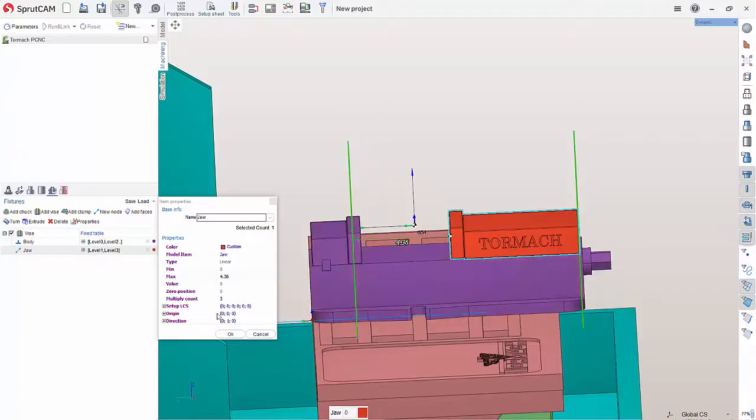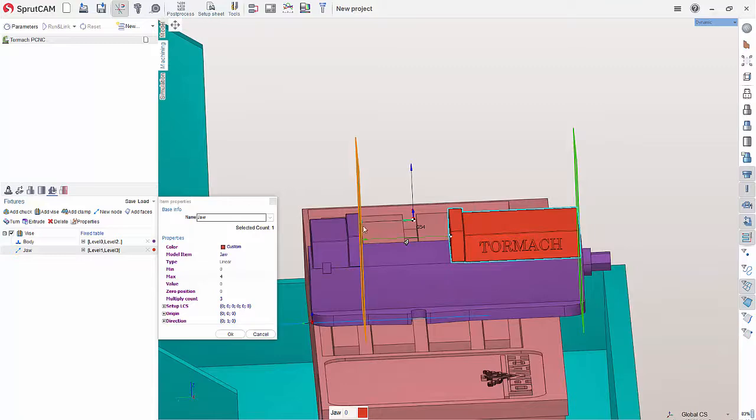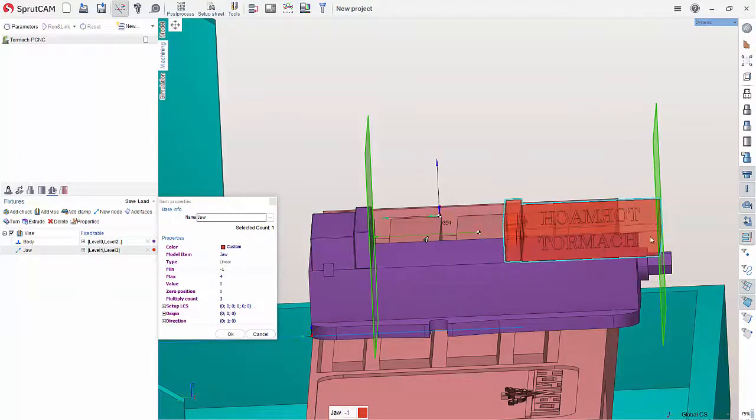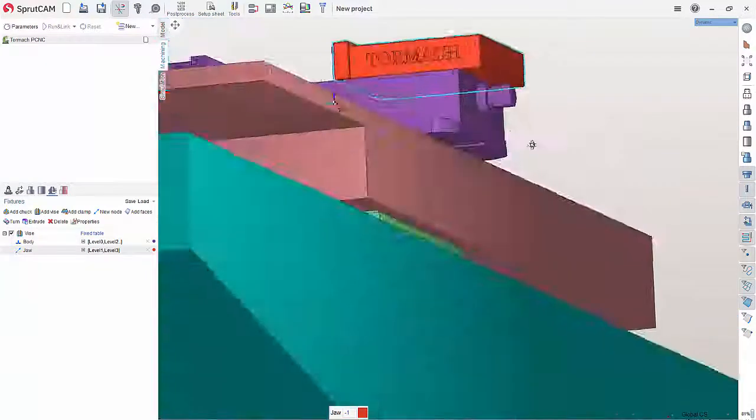Okay, but we want this to be a 4, and that'll take us right up to that point right there. And then because this is a 5-inch, we want this minimum, which is defaulting to 0, to just be -1. And that'll give us that 5 inches of travel that we're looking for. Okay. So once you've got that, you can hit OK.